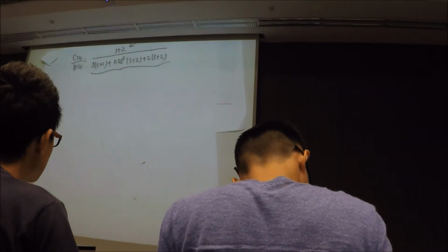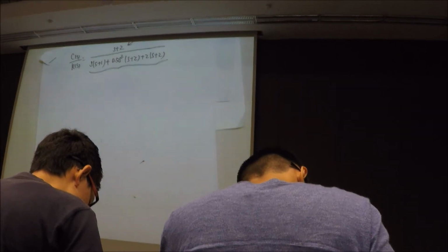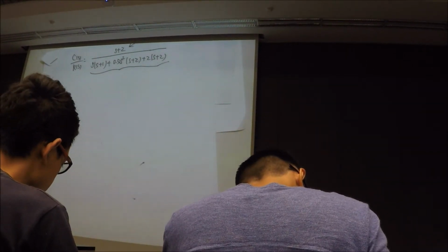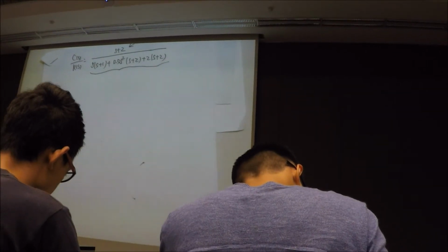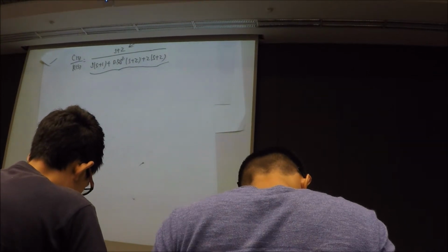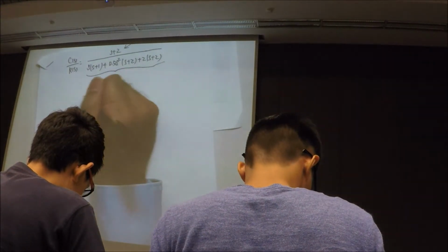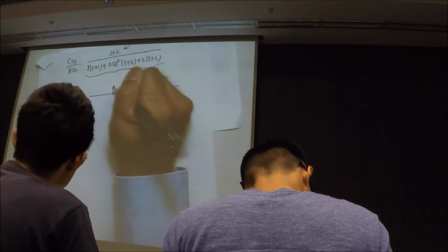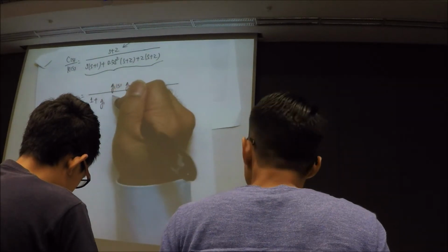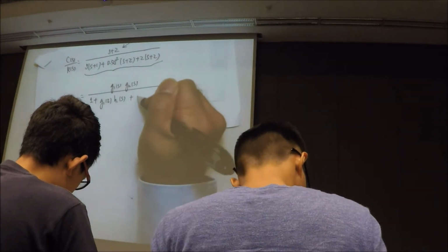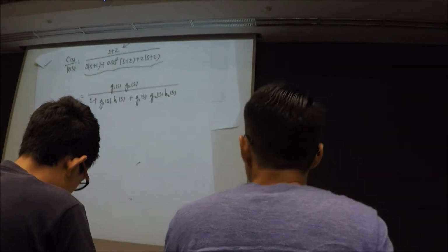But what happened here is, this is a closed loop transfer function, and they also ask you for your open loop poles and open loop transfer function. So what will be your open loop transfer function? I think that will be the interesting thing, because you need to work backward from your characteristic equation. This is one of the things that you need to work on in your tutorial for section 7. You need this G1(s) H1(s) plus G1(s) G2(s) H2(s). So this is your equation here.